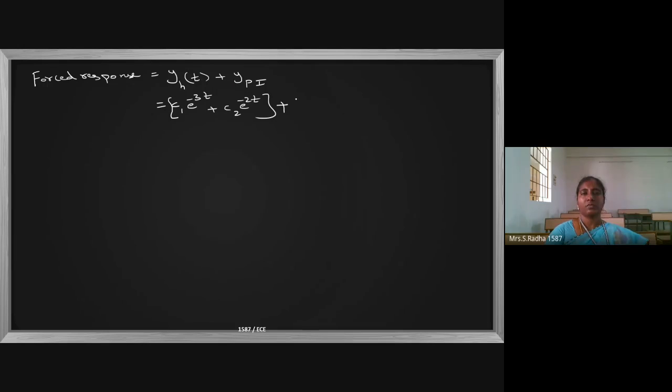So it is 1.5 e power minus t u of t. Okay, this is about forced response f of t. I am making this as equation 4. So forced response means input exists, and initial conditions are 0.